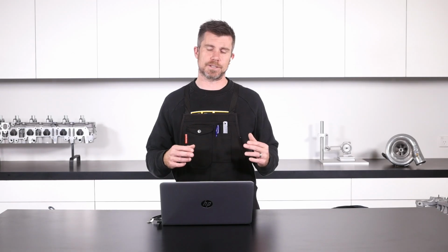Because what you will find, and this is really common with the RB26, let's say we've got stock turbochargers on it, let's say we get it onto the wastegate spring pressure, the minimum pressure, and let's say for example that we can do a run through there at maybe 12 psi of boost. With the Alpha-N style, it actually becomes really easy, because at wide open throttle on the ramp run, we are only tuning that one row through our fuel table.